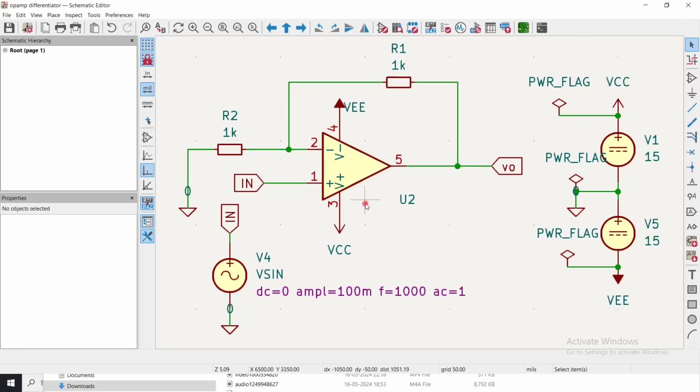I will explain the step-by-step method, because when I was designing this simple circuit, although it is simple, there are some complexities associated with the DRC, that is, design rule check, the simulation commands, and even picking up the components and devices from the library and using the correct SPICE model, whether it is a generic model or a model provided by the manufacturer for the component and devices.